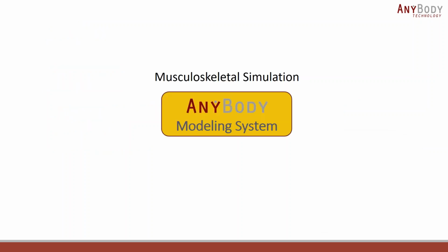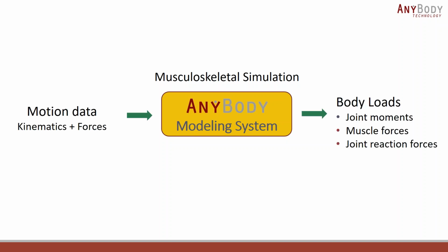So the very first thing I would like to mention, the title says that simulations as a tool for exoskeleton design. So the class of simulations that we are going to talk about is called musculoskeletal simulations. And what it means is that it's a rigid body dynamics analysis which uses motion data and external forces acting on the body as an input.